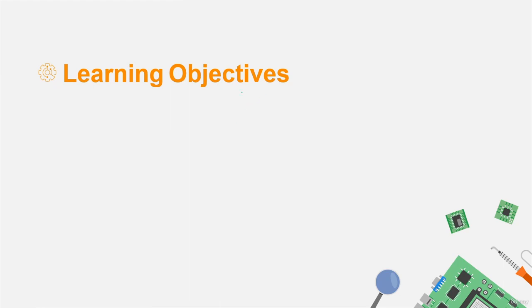Now here you will have a question: why do we have to modify those libraries? See, the reason is we have downloaded those libraries from an external website, okay? And it might happen that we might not be happy with the symbol and the footprints of those libraries, okay? So in that case, we may find a need to make changes in the symbol and in the footprint of the library of that particular component, okay? That's the reason I have dedicated a separate video to the modification of the library.